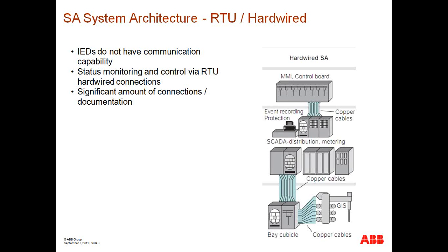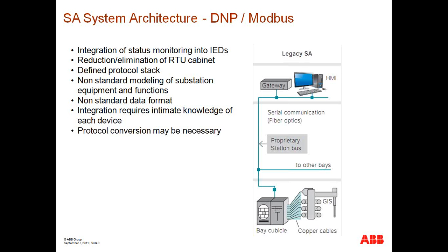One example is the position of the breaker, the 52A and 52B contacts. There are hardwired signals from the A and B auxiliary contacts of a particular breaker over to the RTU, so that the RTU can report up to SCADA the position of that breaker. In turn, there's also wiring from those same A and B contacts over to a protection relay, which needs that information, for example, to understand whether the breaker is open or closed, to execute a reclosing sequence on a particular breaker. So this is again one example of where we have this replication of wiring.